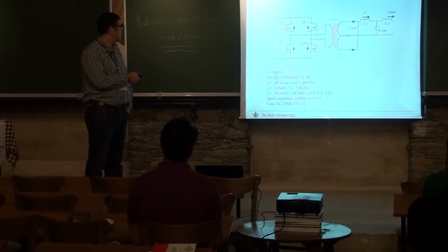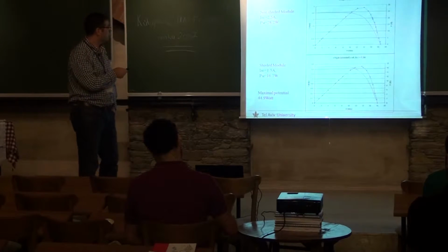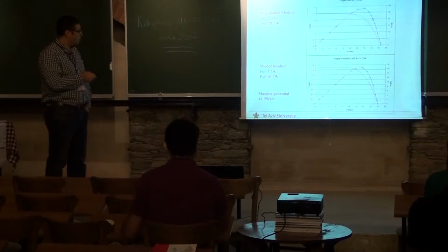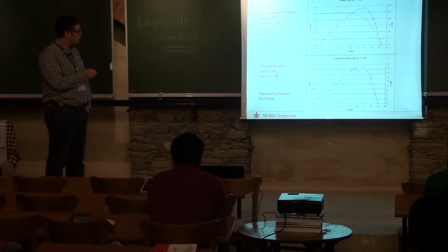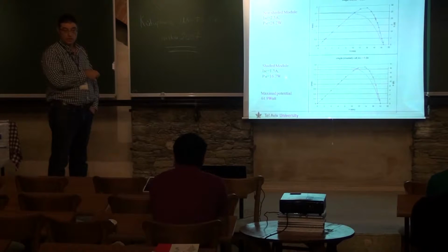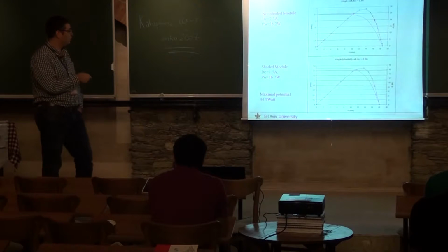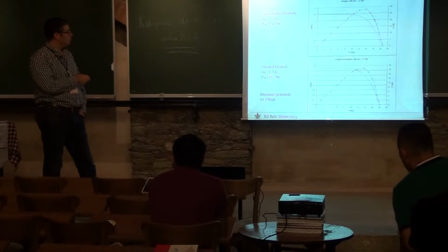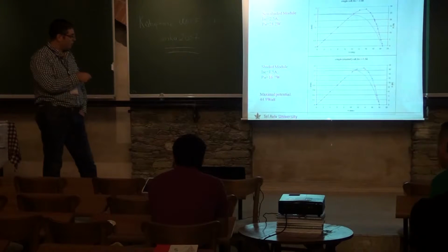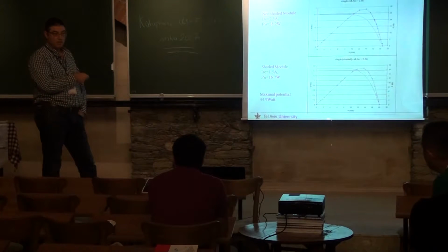Thing is, these are the two modules. So comparing this one to this one, this is 40% shaded, right? Because its short circuit current is 40% less. So that's the power that's going to be injected across this module. So that's 40% of one module, which is 10% of the entire installation, going through an 80% efficient converter, right?